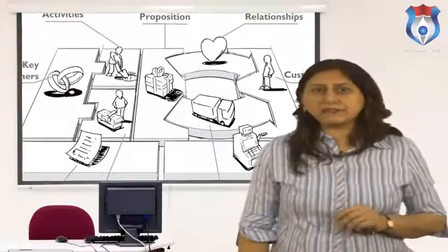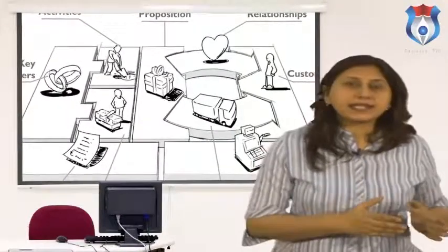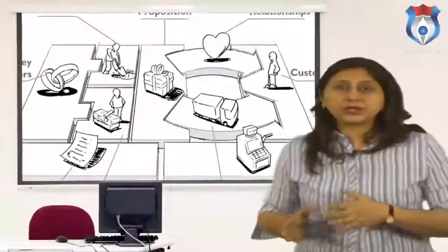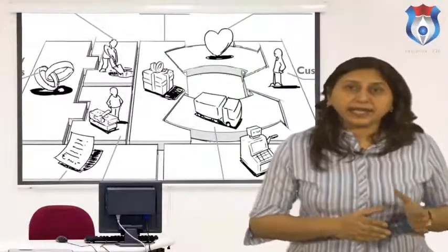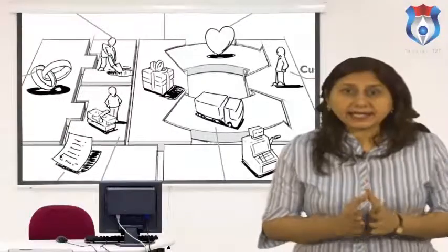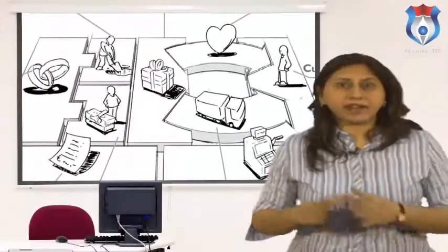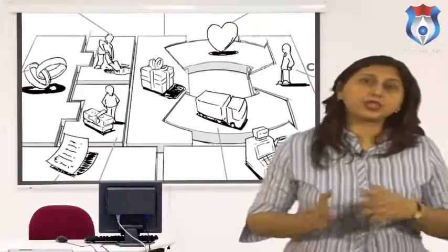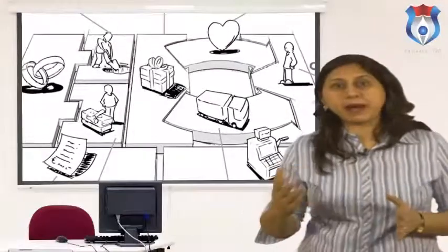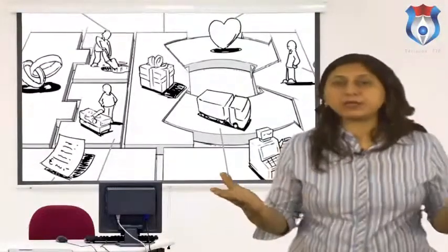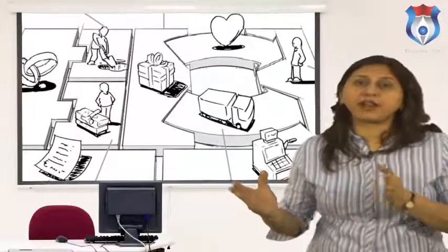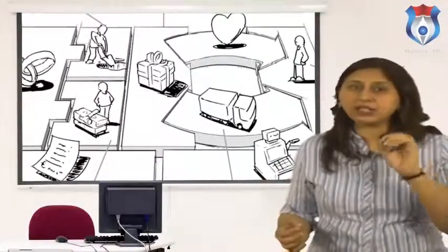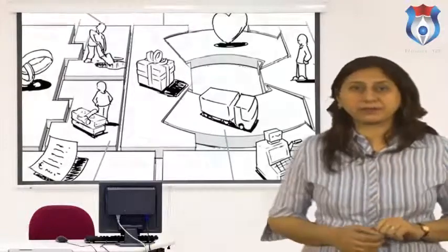How do entities flow through the system? Translate these conceptual models to simulation software acceptable form. Verify that the simulation model executes as intended. Verification techniques include traces, varying input parameters over their acceptable range and checking the output, substituting constants for random variables, and manually checking results and animation.